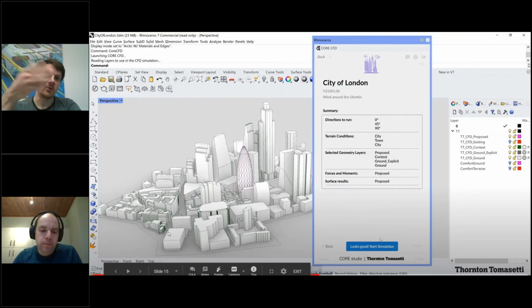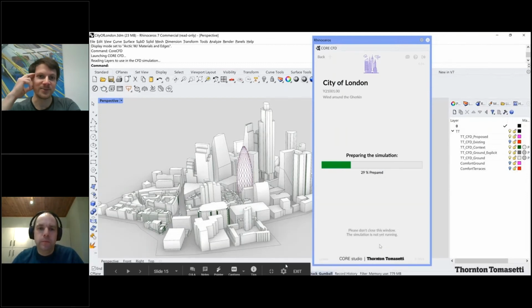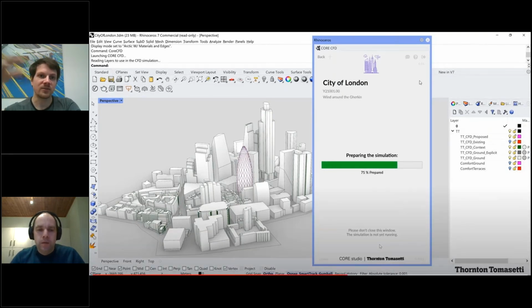So you say maybe you go back a step, you maybe just decrease the mesh fineness, which is easy, which is just a drop-down menu, right? So anyone can do it, and you just check again. Is this now within the budget? And then you can do more detailed simulations later and all of that.